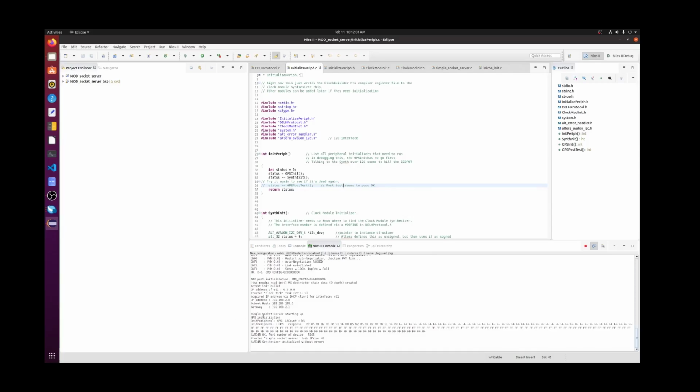It's initialized the GPS module, and the response message 6205 twice indicates that it accepted the GPS initialization commands and has programmed the GPS module into the correct mode, putting out the right reference frequency on the clock and putting out pulse per second. You'll see the pulse per second LED on the clock module start flashing once per second.